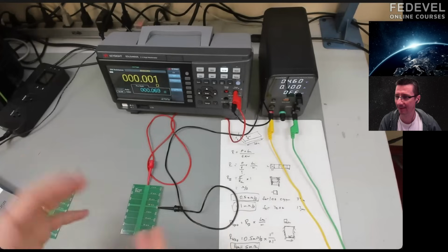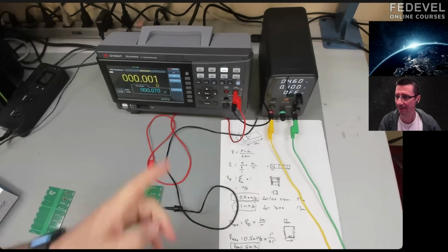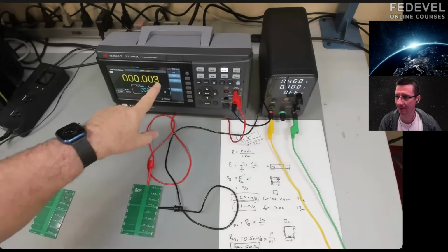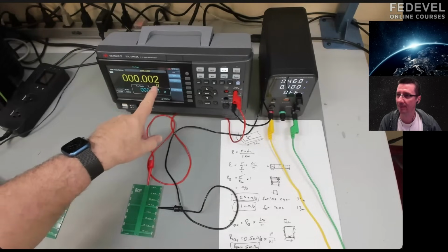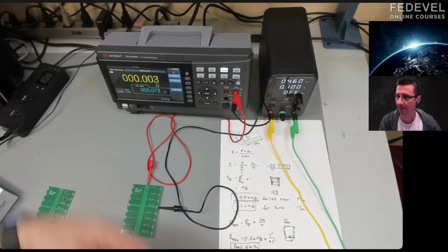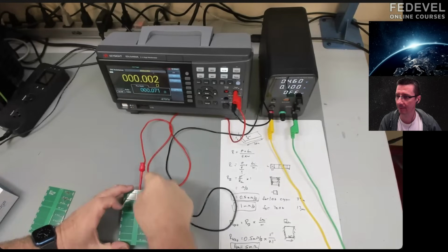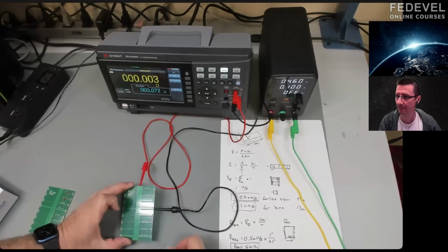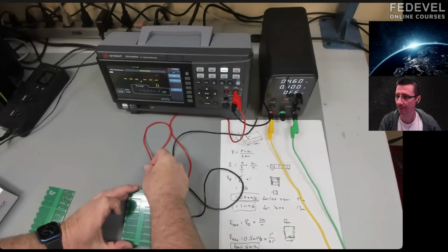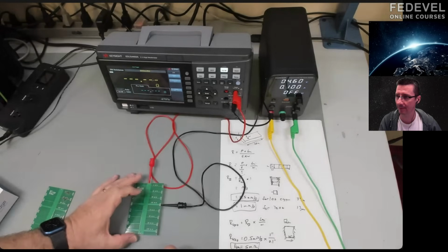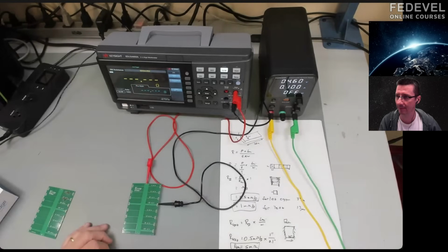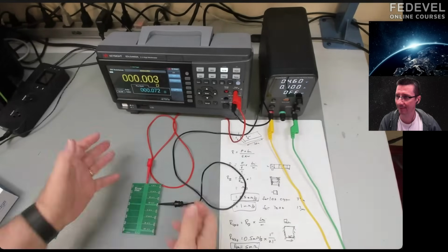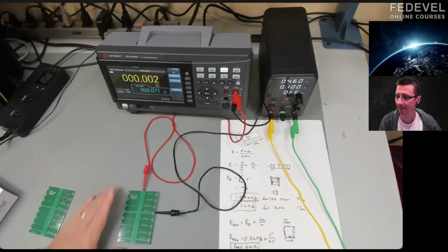So when I'm measuring a small resistance, first of all, this ohmmeter is a great ohmmeter. It's a wonderful box, but it can only measure in the plus or minus 2, 3 milliohm kind of range. And that's the uncertainty, and that's the order of the number that I'm trying to measure. And I've got the resistance of the wire to worry about as well, and the contact resistance of the lead that I'm making down here. So every time I connect it in, I get a slightly different number because of the contact resistance and the small numbers I'm trying to measure.